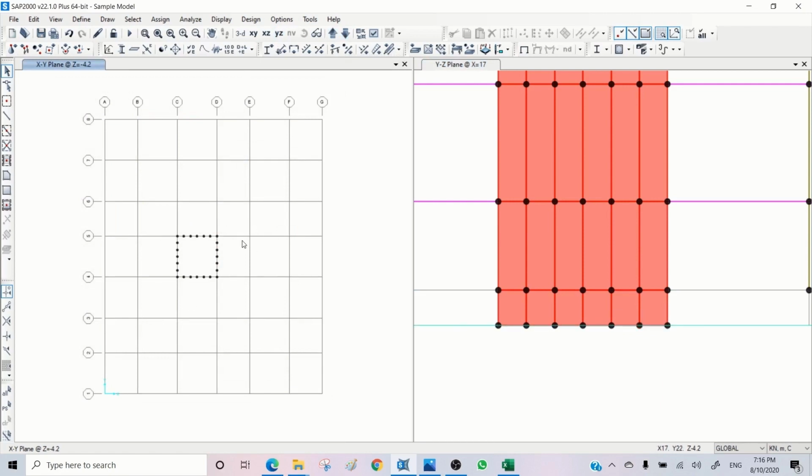Now I want to draw the lift pit wall foundation. Again, it's really back to the condition. Sometimes lift pit wall is bigger, sometimes if it's on the rock, sometimes they just draw vertical cut and have a lift pit wall completely confined between rocks. Sometimes they want to have drainage around to ensure there is no water seepage later into the lift pit. So we assume that we have a foundation a bit wider than lift. So I will consider, say, 500 millimeter each side wider, so plus 100 millimeter thickness, that would be 600 millimeter each side. You can simply come and draw a foundation here like this, because you already have these edges.